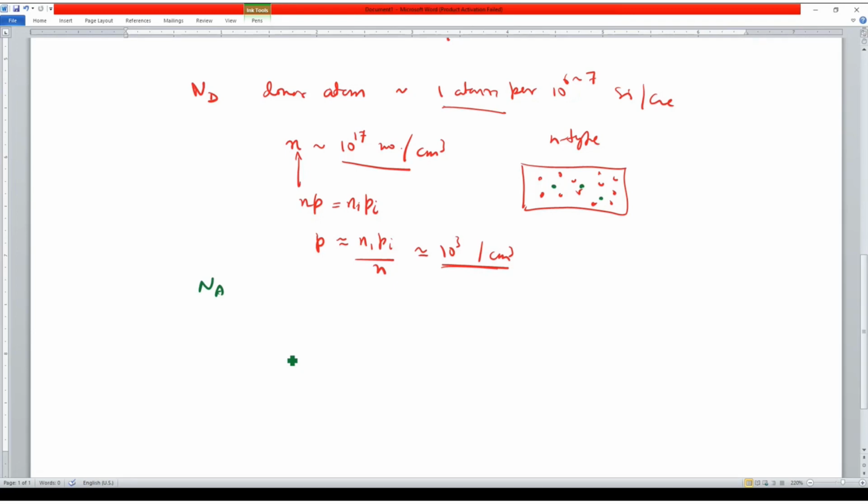So it will pick an electron from a nearby silicon atom, so that the vacancy goes to that silicon, and that silicon is again deficient, and it will try to accept an electron. Further, as the electron goes on moving, the vacancy is moving, and you can depict that the hole is moving. So a hole is not exactly a real thing, but it is inferred from how the vacancy is transferred from one silicon to another silicon.